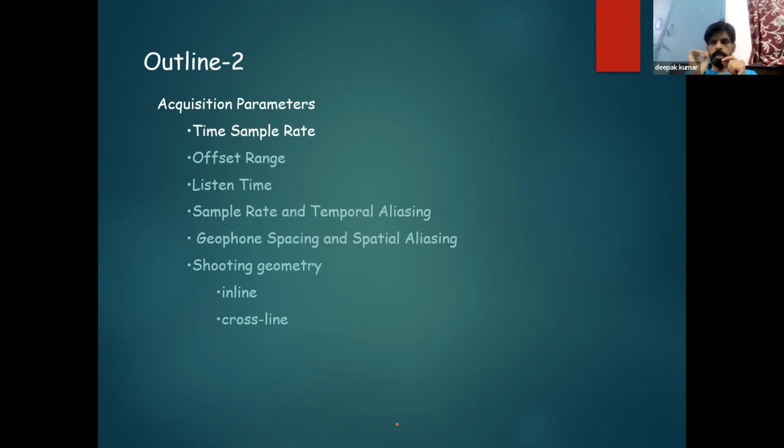So what happens is, if my sampling rate is higher or lower, it will create some kind of noise, or a repetition of the higher or lower frequency after a particular frequency. Suppose my total frequency range is 100 hertz. The midpoint is 50 hertz, so that frequency of 50 hertz becomes my Nyquist frequency, meaning the maximum allowed frequency. After 50 hertz, all other frequencies are just a repetition of the lower frequencies, lower than 50 hertz.